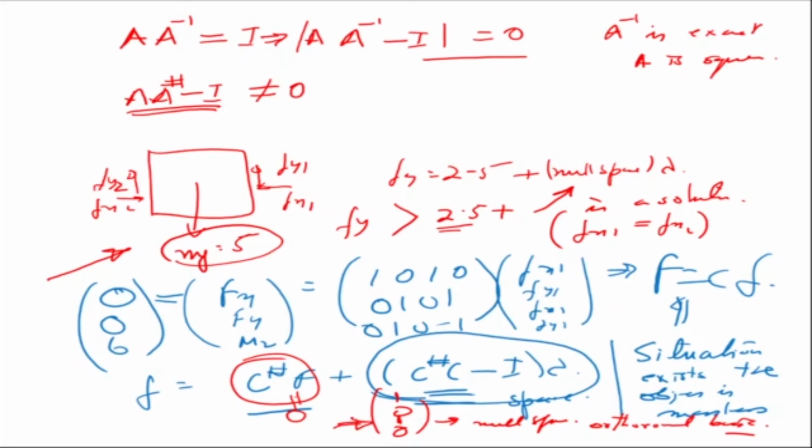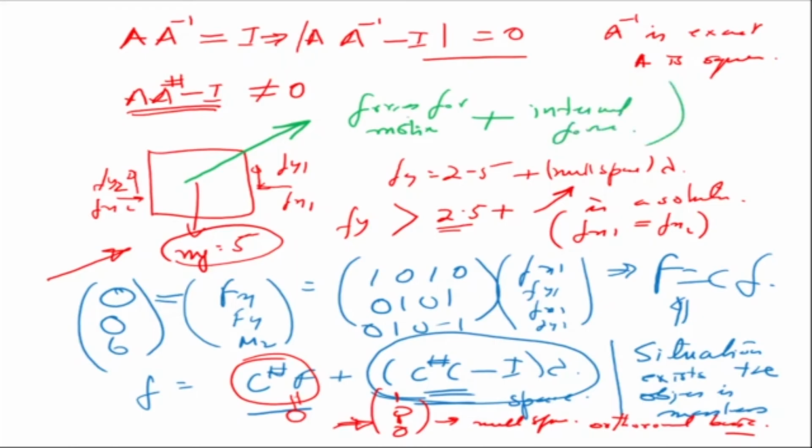That means even if you do not have any force here, you still require this to hold the grasp. If you think a little bit on this, if I want to grasp an object and move it somewhere along that direction, I have grasped an object and I want to move it like that. To move it, you need to apply forces, and to grasp it, you need to have internal forces. So the total force will be the forces for causing motion plus internal forces. So you need to grasp the object and then move it along in some direction, so you need components of two forces.